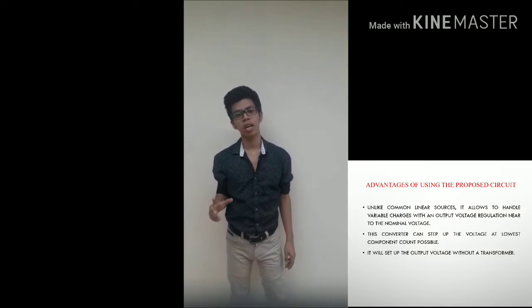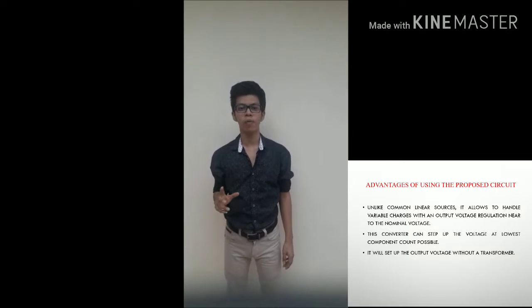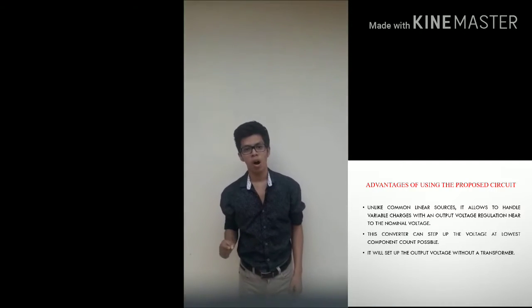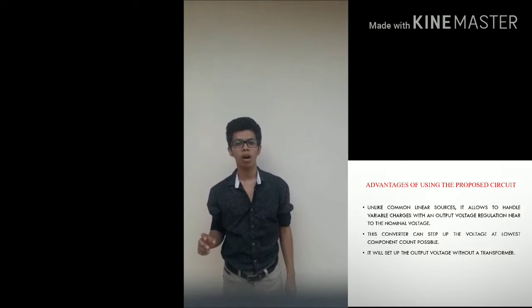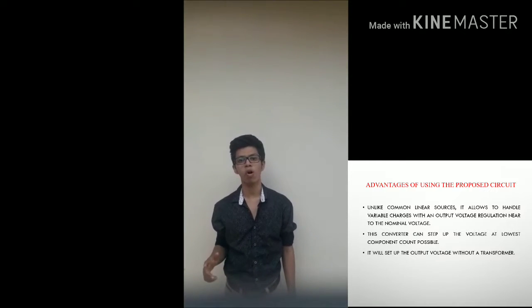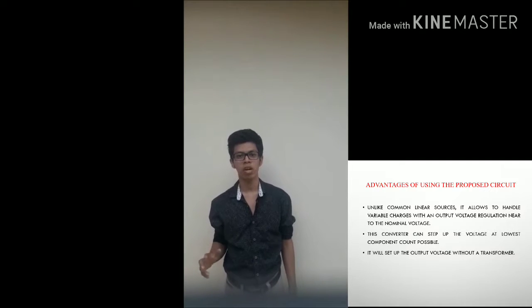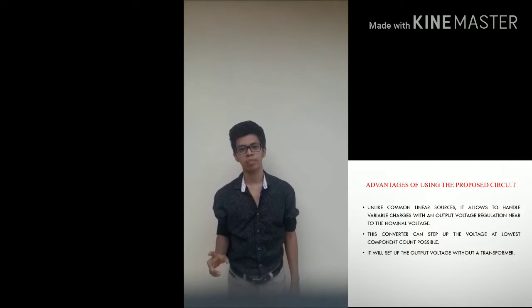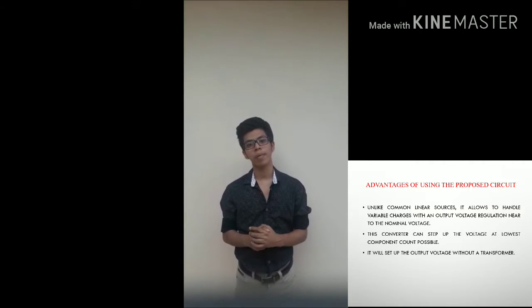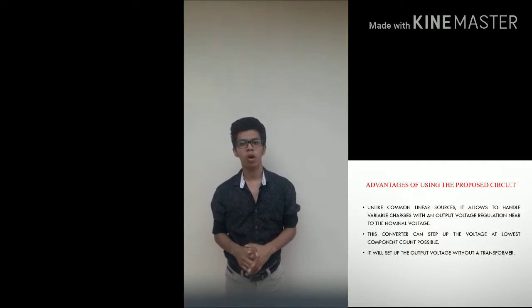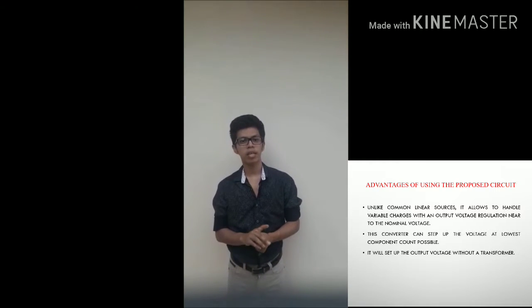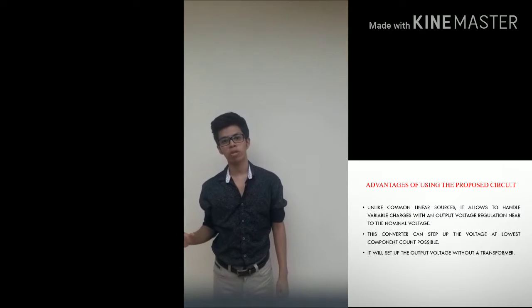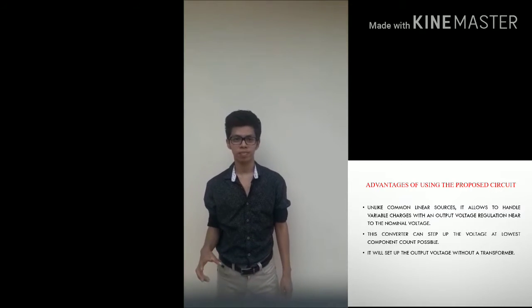At this moment, I will tell you of different advantages of using these circuits. Number one, unlike a common linear source, it allows handling variable load with an output voltage regulation near to the nominal voltage. Number two, the converter can step up the voltage with the lowest component count possible. And the last is that it sets up the output voltage without a transformer.